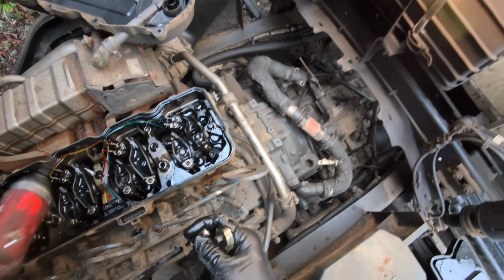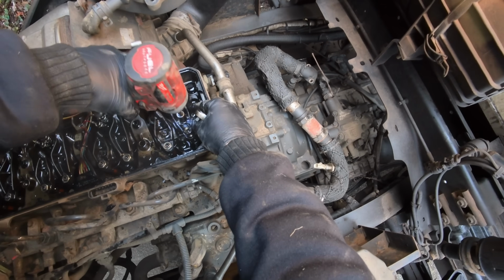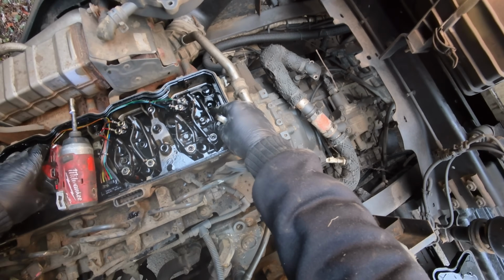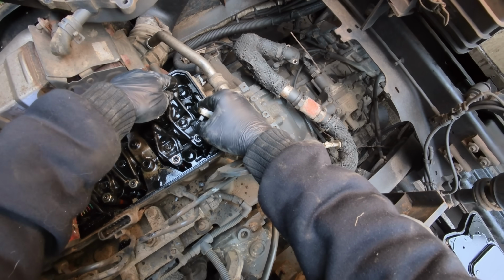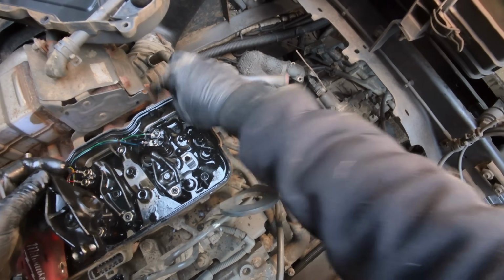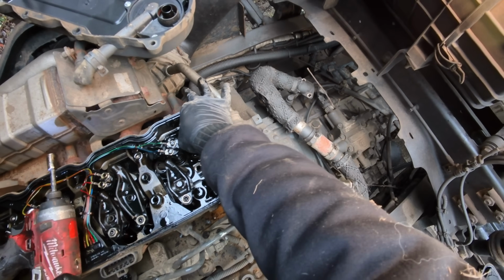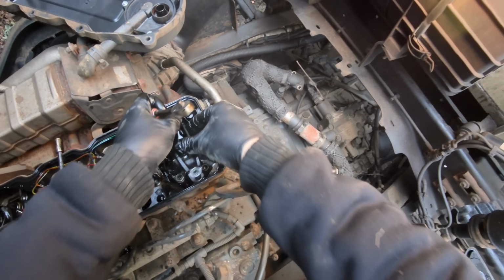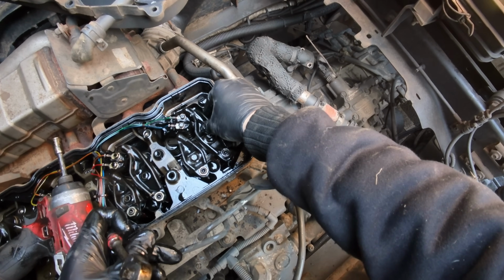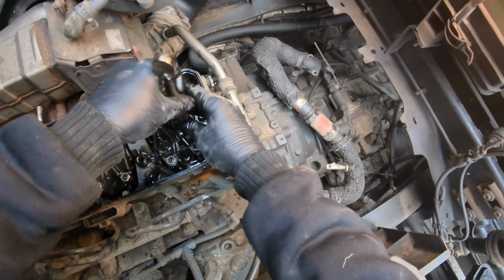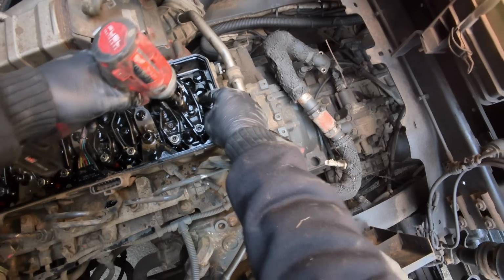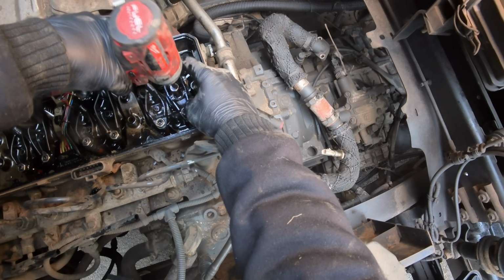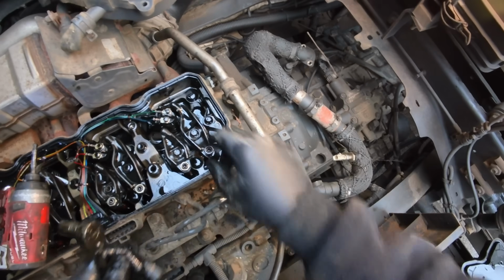Right, so we'll just have this rocker lever up out the way. We'll put our bridge or crosshead back on. We'll pop this back down. We'll run that back in and torque it up. There you go, don't want to snap it. Now we'll turn the engine over, set it to TDC and adjust number 6.